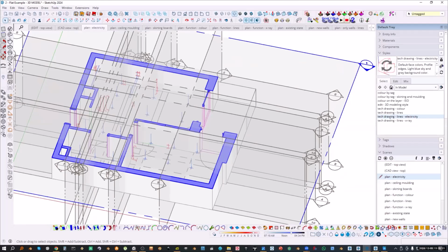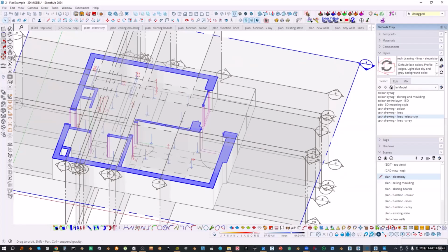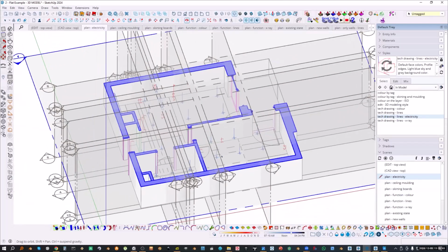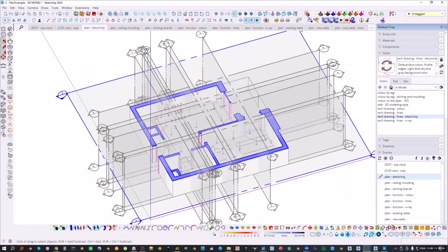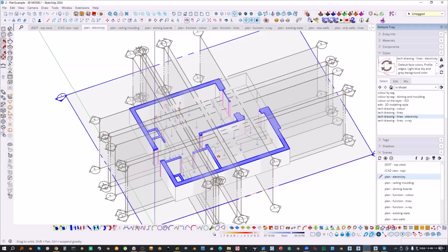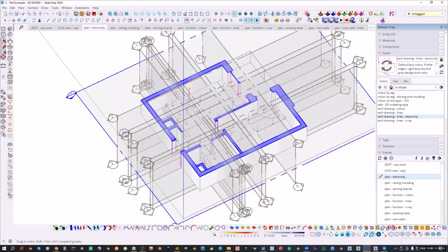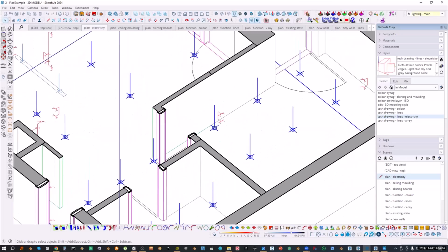So as you can see, I have multiple styles. So always remember that if you are planning to work in layout, you really need at least 2 or 3 styles inside of SketchUp. You use one for the editing, for the modeling, and you use at least 2 more, the linear and the colors for layout. Otherwise, if you are just using one, there will always be problems. The sections are going to disappear, and you will be very annoyed. So that's the reason for the projection on the lamps.